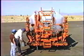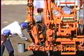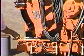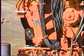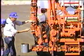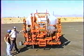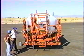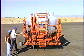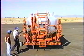If you trace it out here, we're coming from this feed hose. If we go directly through this equalizer valve, material can actually go back out to the end of the wing here and up through the internal tube in the opposite direction that it was going when we were circulating. Same on the other side, so now we're feeding the wing through both the internal and the external passage. Essentially, we're feeding the spray bar in 4 major places, each end of the main bar and each end of each wing.